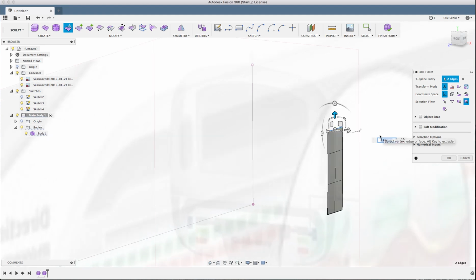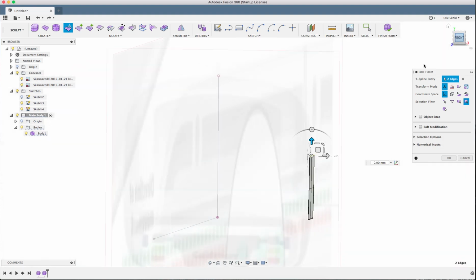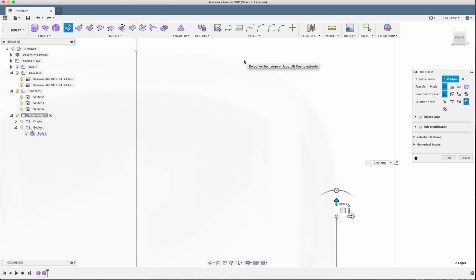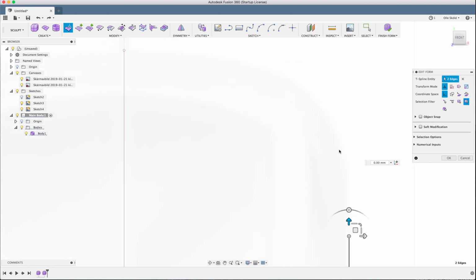So now I will press Command Z to go back, because at the same time I'm creating new faces, I'm gonna try to follow this really dim line here. So let's hold the Alt key, and we hold this big square, and now I can release the Alt key because I already have the new face. And I just go up a bit and release it, and then I press the Alt key again, and I click and drag. Now I can release the Alt key, and I repeat.